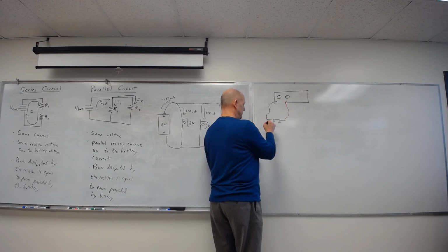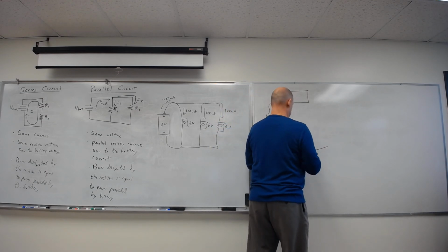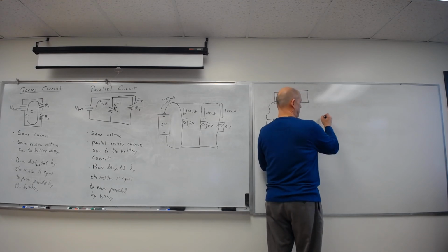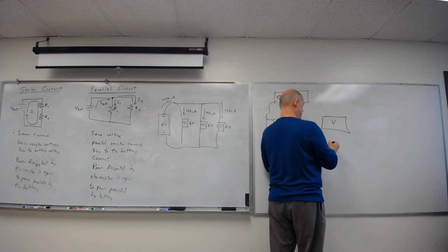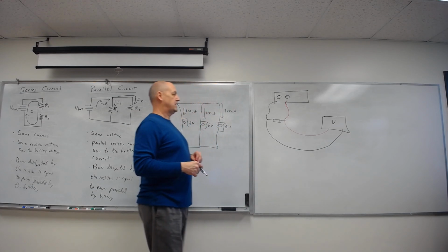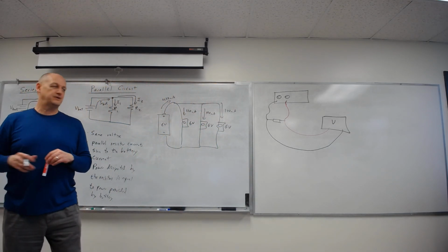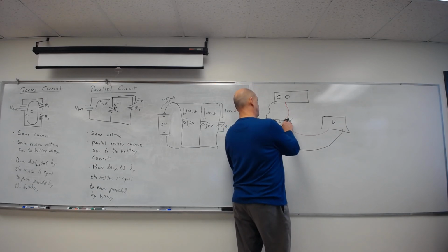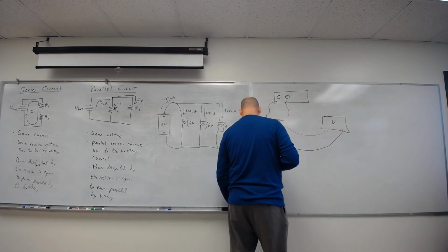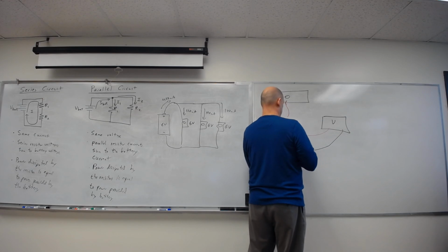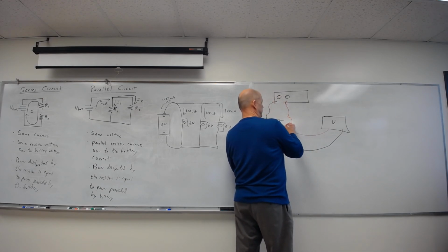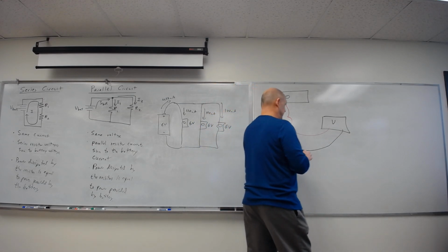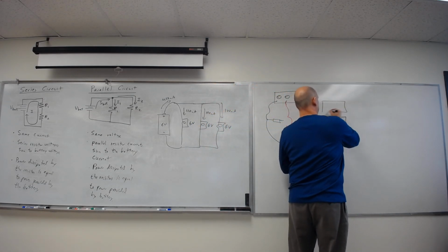Well, I take a wire and a wire and go over to the voltmeter, which is the one I'm picking to use as my voltmeter. I can measure the voltage then, and I can set it to 2 volts or whatever. And I want to measure current, so what am I going to do? I'm going to disconnect those on one end or the other, it doesn't matter which end. I have those connected together, probably some alligator clips or something. And then I'm going to take my ammeter over here, set it up to measure current.